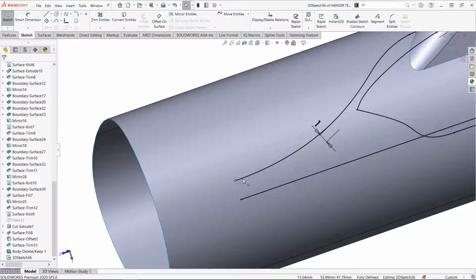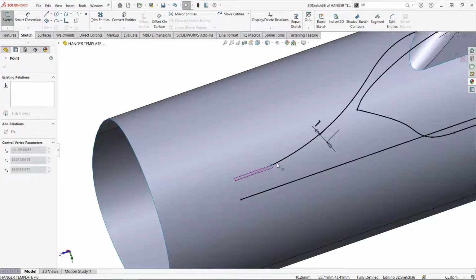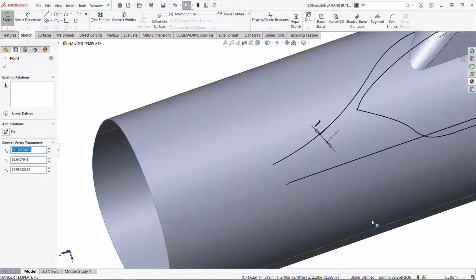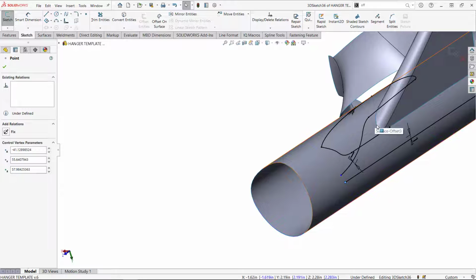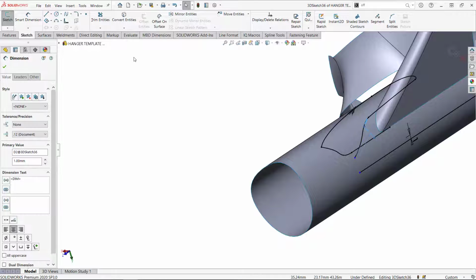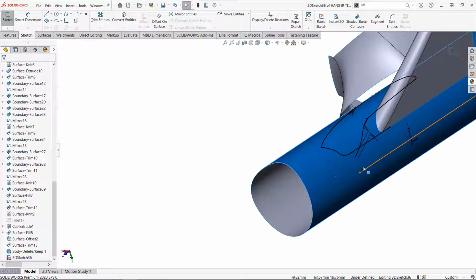So for example, I would like these 2 points to move, right? So notice I'm detaching them, similar to the offset in a 2D sketch. Why? Because I would like to create this type of edge on this area over here and give me something that I can play later on. I can adjust by moving this, right? So let's use a spline on surface. And this is the reason why I wanted to create this extra body.